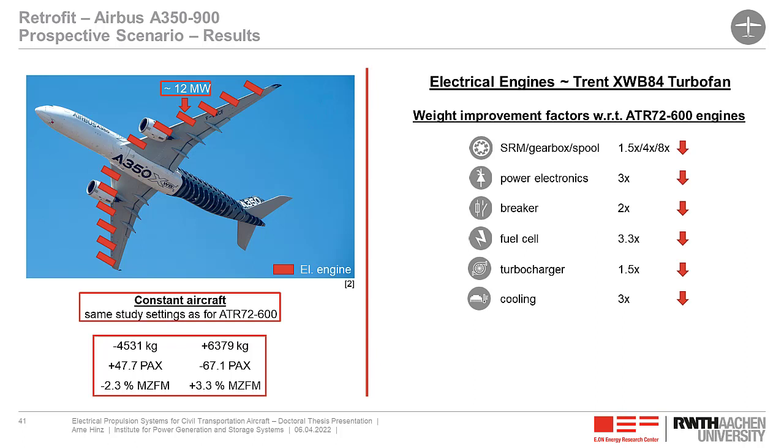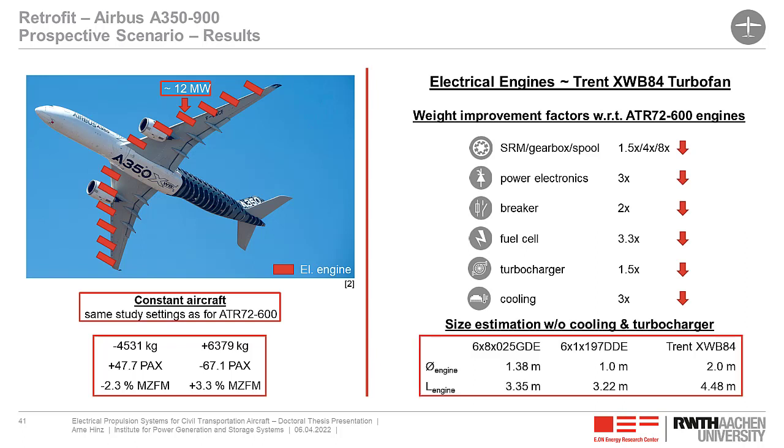We actually put 2 engines of the Airbus A320neo in a row. So that's why the engine spool needs to halve with respect to the Airbus A320. Regarding the size, as said, we put 2 A320 engines in a row, so the diameter stays the same. Again, the direct drive engine could be acceptable. The gear drive engine should be reconfigured.